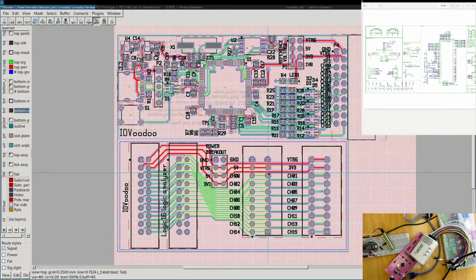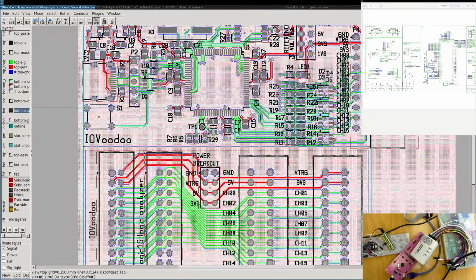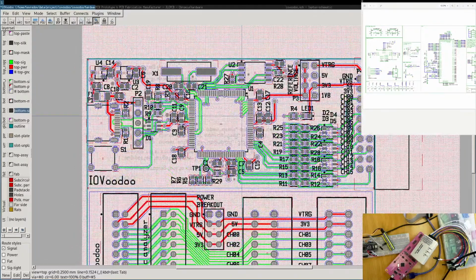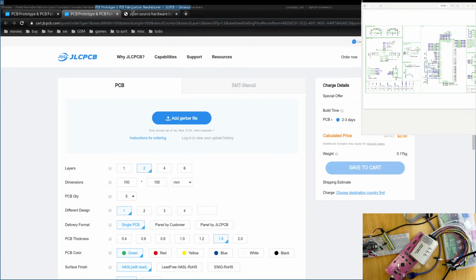Once you've done these verifications with the routing and the DRC, routing meaning no net is colliding and everything is routed, then the DRC to check if it respects the rules, then you have to check the solder paste, silkscreen, which the DRC cannot do, and the top soldering mask, which a DRC cannot do. This is just human. Then you are almost finished, but not finished yet. So let's save this.